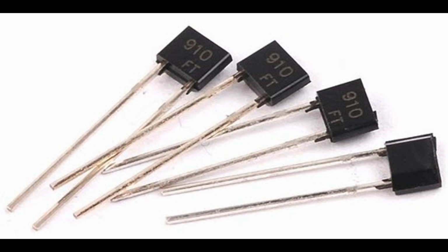Varactor diodes are available in various semiconductor materials, such as silicon and gallium arsenide, and their characteristics can be optimized for specific applications by choosing appropriate materials and designs. The ability to control capacitance with an applied voltage makes Varactor diodes versatile components in RF and microwave systems, enabling precise frequency control and modulation in various electronic circuits.